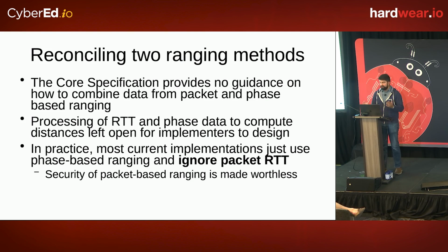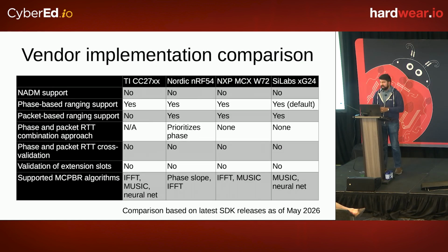And so if you're just throwing away the security of the packet-based ranging with this, and the phase-based ranging doesn't even have validation of the extension slots, then it's not really secure ranging as is. So I examined a bunch of different vendor implementations from TI, Nordic, NXP, and Silicon Labs.